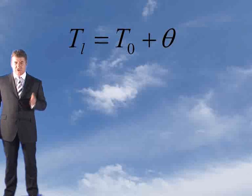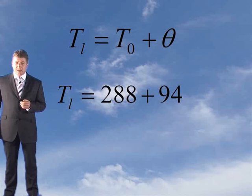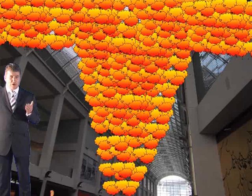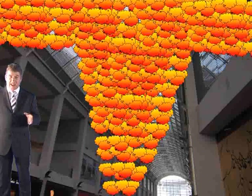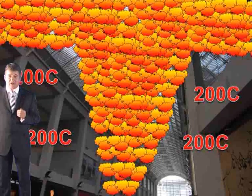Now we need to work out the absolute temperature of the smoke layer using this formula, where TL equals T0 plus theta. If you'd put them in, you'd have got a TL, a temperature of the smoke layer, of 382 degrees Kelvin. Now, don't forget, it's important to remember at this time that there's a life safety system, and the temperature of the smoke cannot exceed 200 degrees C.